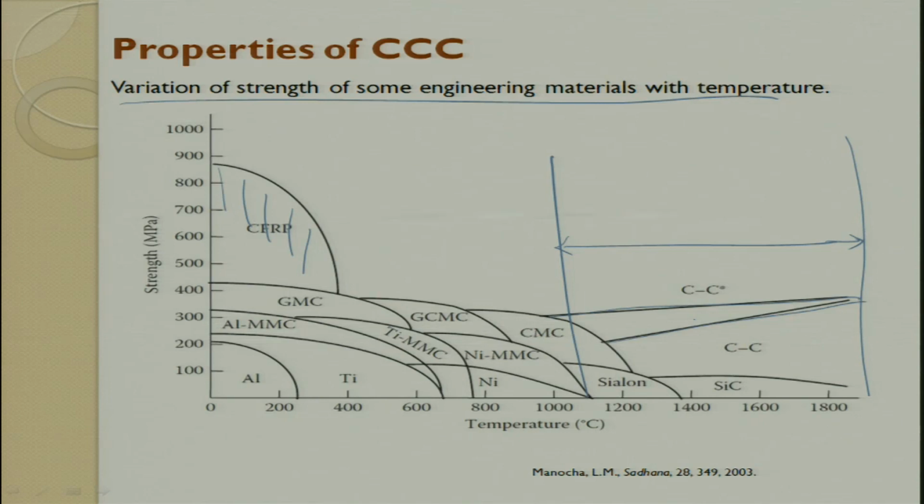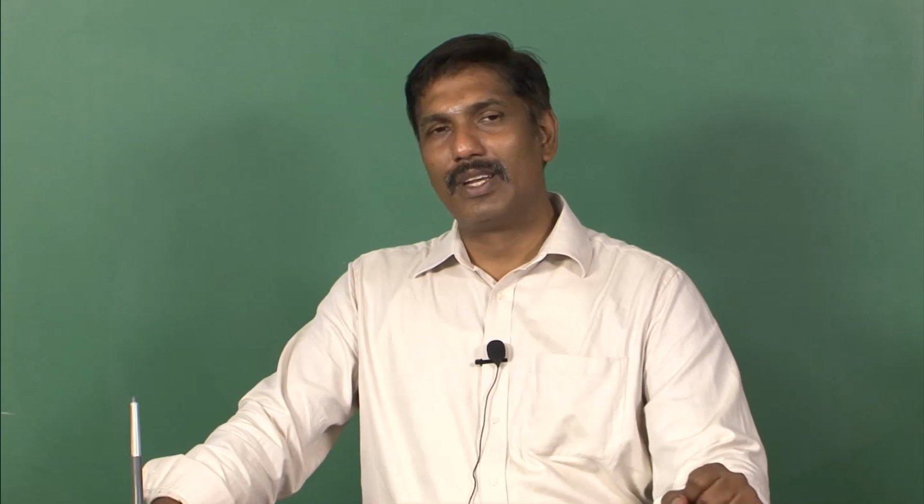With this, we come to an end of this carbon-carbon composites fabrication, and we have seen different properties. Predominantly here we use thermoset matrix, thermoplastic matrix, then we use CVI. In CVI we have seen 4 different variations to reduce the cycle time and to enhance the quality of the output. We can also do exclusively CVD, but there are a lot of limitations in this process. That is why we do not use CVD to a large extent. We follow only the CVI process to get carbon-carbon composites. Thank you very much.